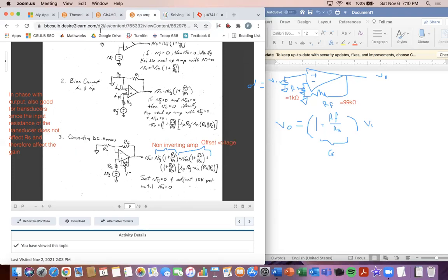And then also down here is the input bias currents. So in this final equation, the DC error, it combines the offset voltage, the input bias current equation, and the regular non-inverting amp equation. Okay, so that's why you have a potentiometer here. So when you have 0 volts input, it accounts for this offset voltage and the input bias current because you're able to set the voltage output equal to 0. So they do not affect the value when you actually do have voltage coming into this regular non-inverting op amp.